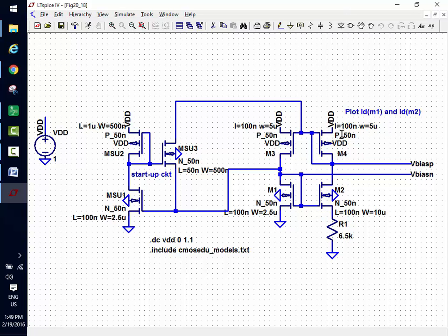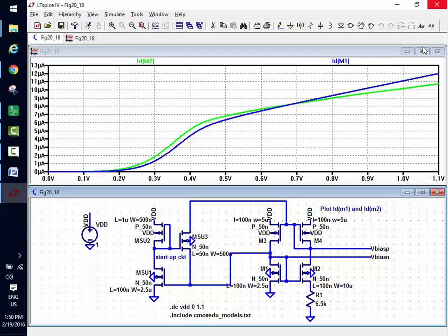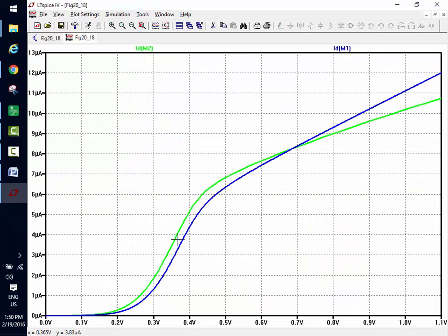And we know if we sweep VDD, which we're going to do now, we want the currents to not change. We want them to be stable. And if you look, that's not good, is it? Currents are not stable. They're changing quite a bit, maybe 50% with changes in VDD. Does everybody see that?